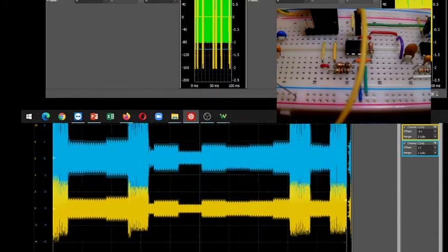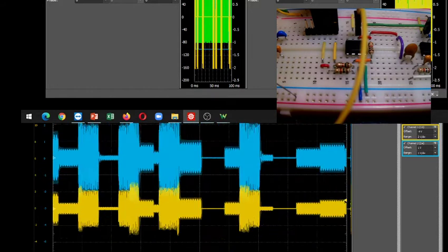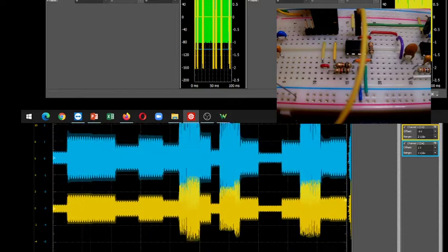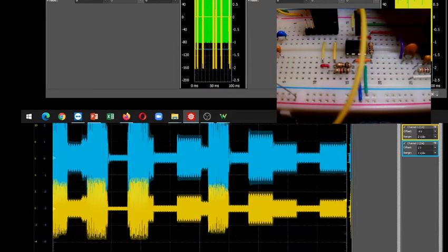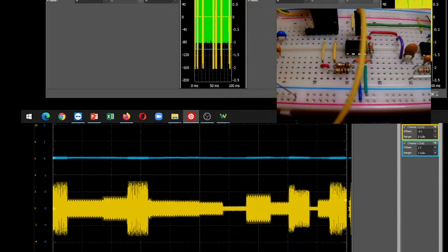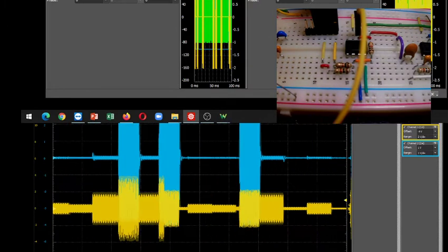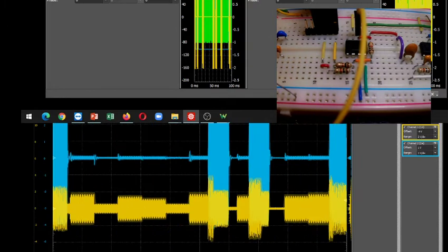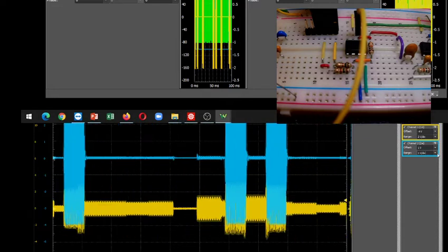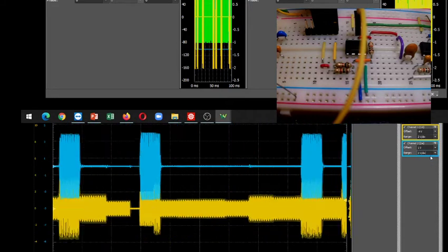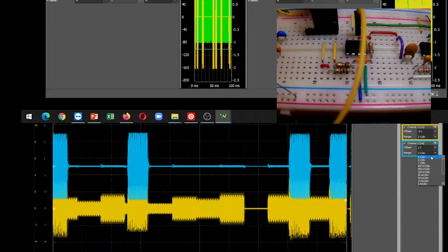However, in the case of additional interference signals with also high-frequency carriers, another filter is needed, a low-pass filter that still allows the message signal to pass through, while attenuating the higher frequency interference signals. Both filters jointly form a band-pass filter that selects a frequency range around the message signal carrier frequency, but attenuates everything outside the band.